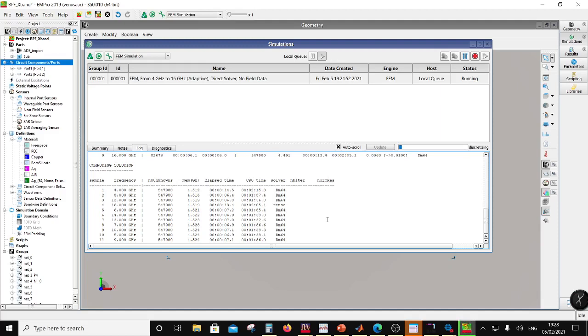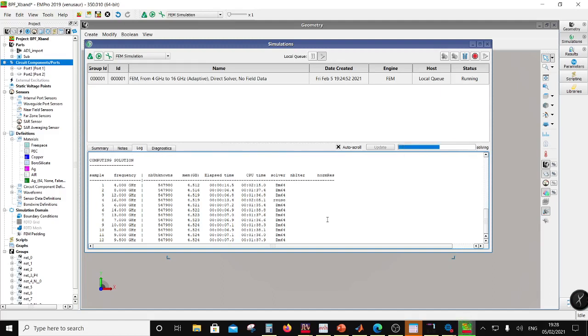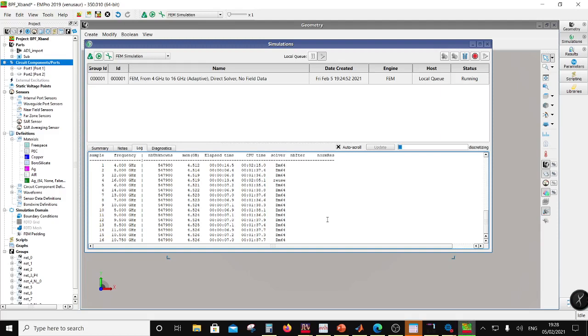It should be pretty close. See, the whole idea is your impedance inverters have to be right, or the capacitance between the two lines has to be right. So spacing has to be right. That's the first and foremost thing. But then there are ways to tune it also. Looking at the response, you can do a tuning, not a blind tuning. The optimizer does a blind tuning. You don't rely on a blind tuning. You should have some idea of the coupling capacitor. The optimization doesn't give you that idea, which this equation design will give you.